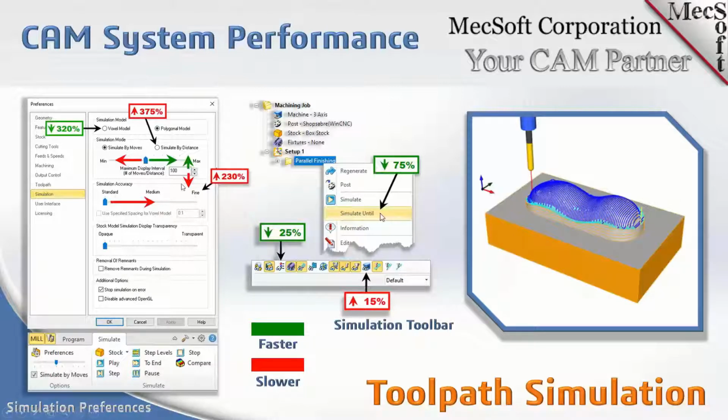You can increase this to, say, refresh every 1,000 moves, and that can really speed up the time it takes to get through a complicated model. So you may see a refresh every, I'm just going to guess, 2 minutes, versus one every 30 seconds. Again, that's by moves.